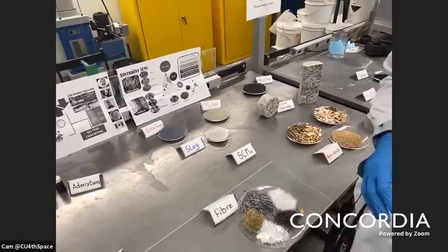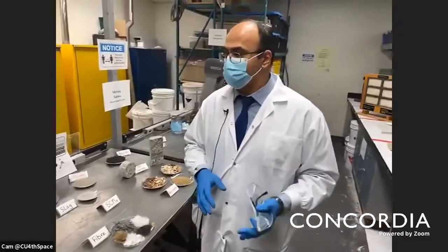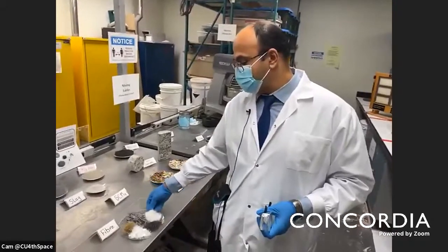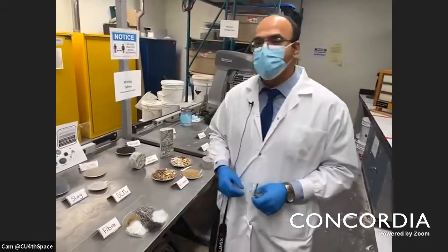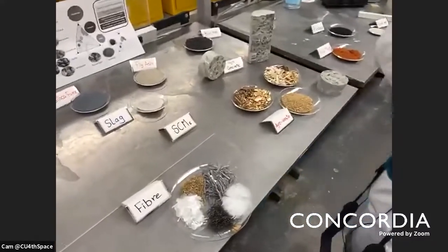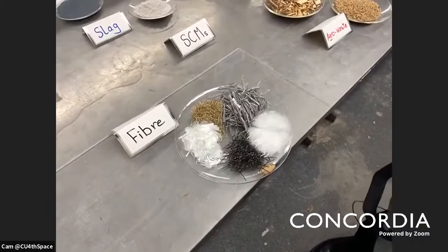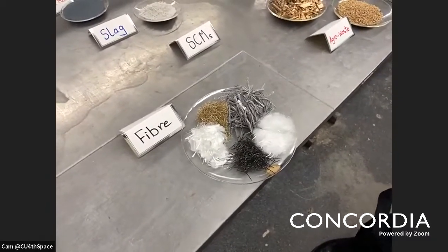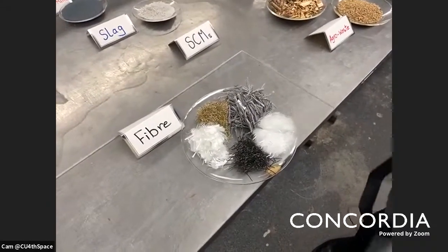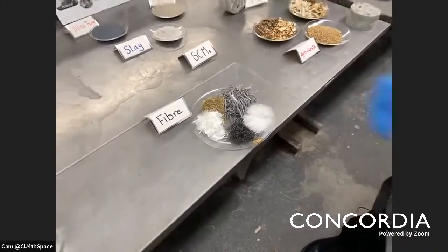One of the main challenges that we face with concrete is that concrete has very low tensile strength. Therefore, we can start adding fibers, and as you can see here, we have different types of fibers, which are going to bridge the cracks, and therefore will delay the propagation of cracks, and consequently will improve the tensile and flexural performance of our concrete.